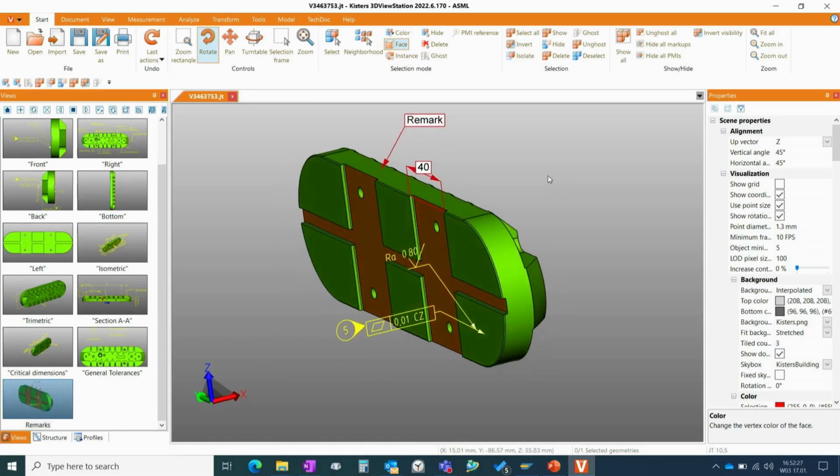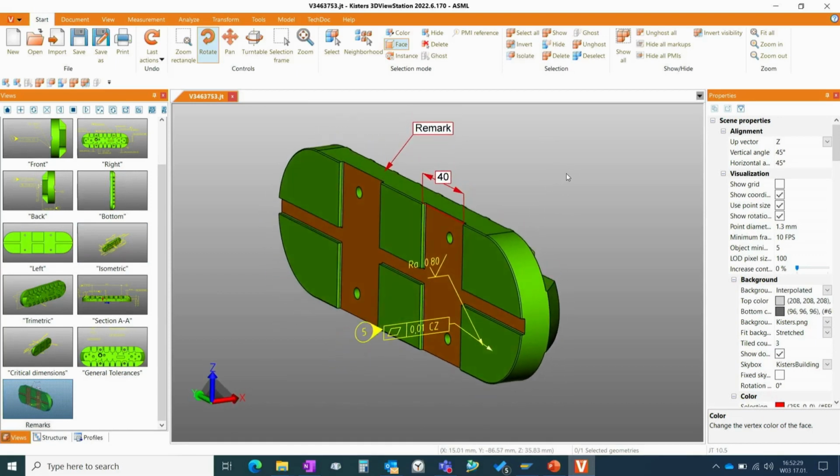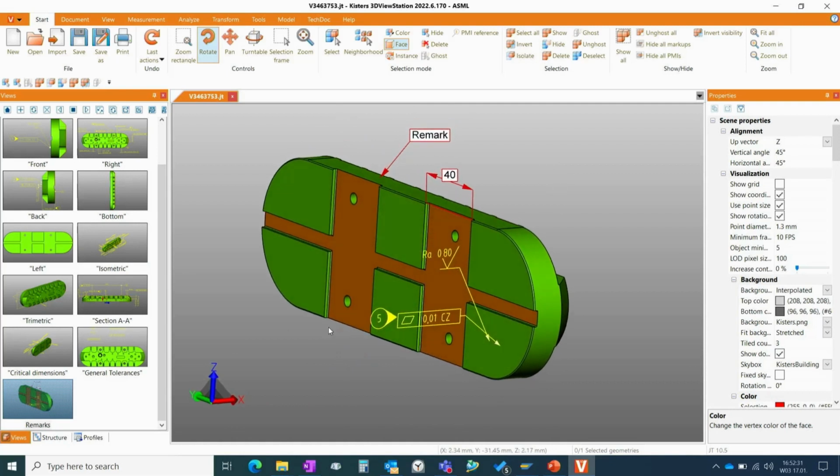If you then later on add more information or manipulate your view, then you just select it again and press here the update button, and then the view is updated with the work you have added. So with the update button, you can add information to all the views. Actually, you can update all the views, but I would recommend that the original views on the TPD you get from ASML, keep it untouched. And if you add your own information, just add additional views.